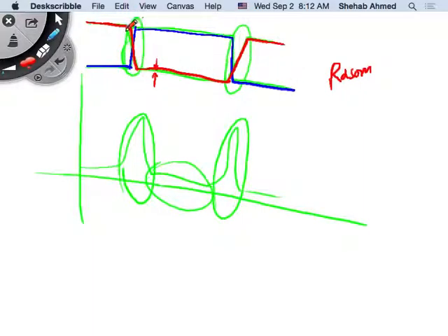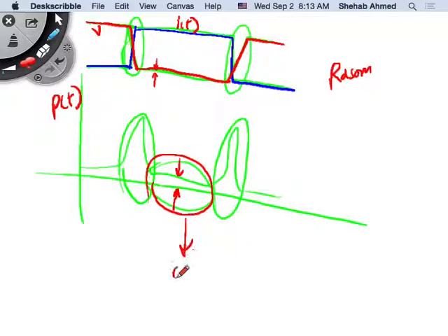During the transitions, we said that currents and voltages overlap. There's a period of overlap, and that's why if this is V and this is I of t, the instantaneous power waveform will look like this, right? When the switch is on, there is a small power loss that's called what? Conduction loss. Conduction loss due to what?